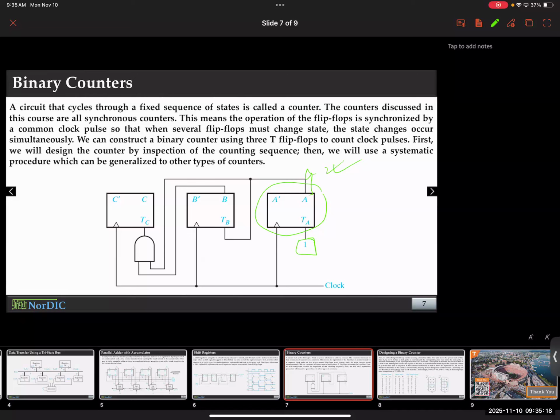All right. Oh, by the way, before we get to this, you have 3 flip-flops. 1, 2, 3. And they're all driven by the same clock. So let's get it out of the way, all right? Clock is basically shared amongst all the flip-flops. That's why they're synchronized. So they update themselves with the clock. The only thing that we have control over, we don't have control over the clock here. It will just keep coming. We have control over the input. We can control the input to make them switch the way we want to. So the first bit, we are making it switch every time. So it is always switching. We deliberately force a 1.